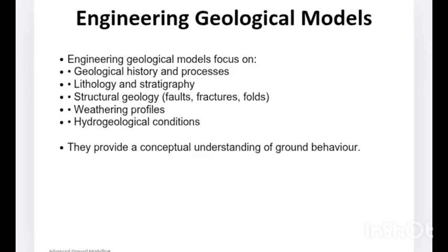They emphasize the interpretation of key components, which include lithology and stratigraphy. Lithology refers to rock or soil type, while stratigraphy refers to the layering and sequence of geological materials. I'm sure you already know that. For example, clay overlying sandstone, lateritic soil over weathered basement rock, marine clay deposits beneath reclaimed land.